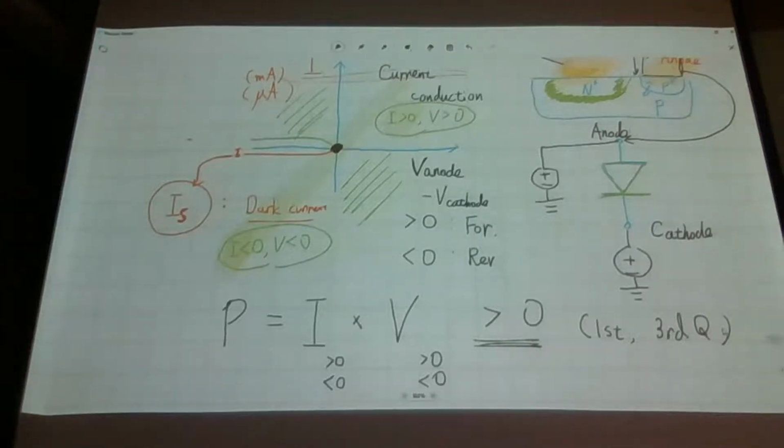It means that your device just consumes the power, uses the electric power and converts it in a different way. So this is just a consumer of power. However, if we are considering a system or an element called electrical battery, then you can find that their IV characteristics lie in the second and fourth quarters. So think about that case. In that case, I and V do not share the sign. So when we make the product between I and V, then what will happen? Obviously, that will give us a negative sign for dissipated power.